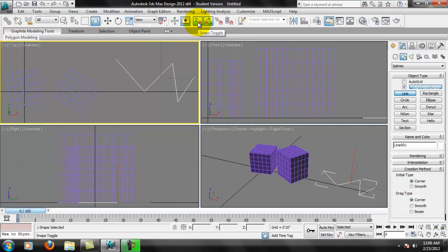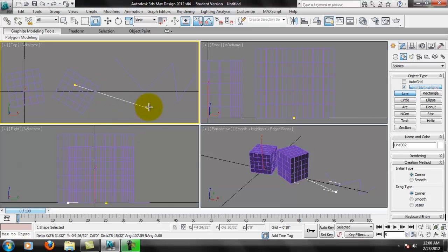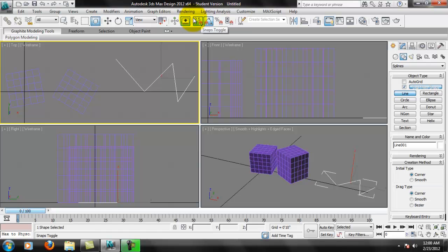Okay, so if I select a 2.5, it projects whatever I have to the plane. So it might show you that it's snapping here, but if I click and draw, you'll see it's actually only drawing on the plane. So the 2.5 projects from the 3D, from the top snap to the plane.